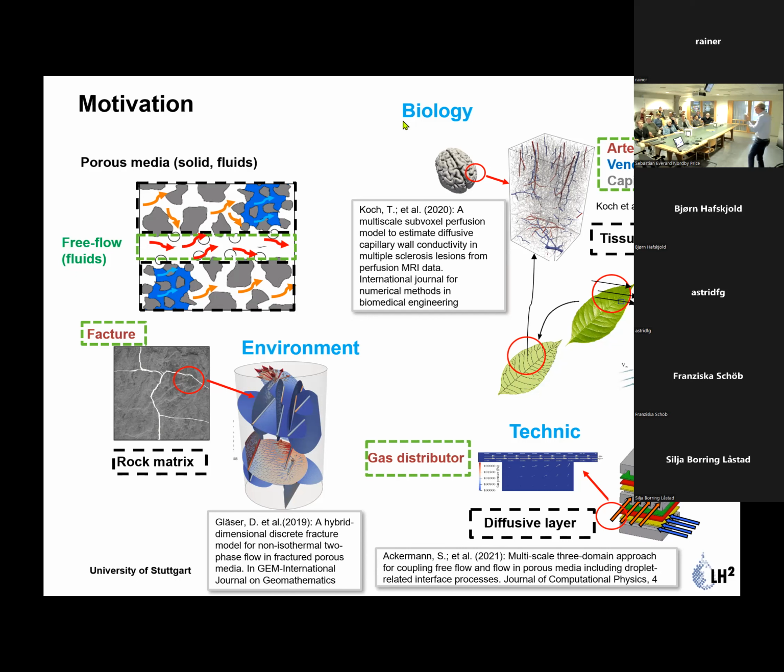There's a big difference to the other ones. In this case, the diffusive layer is a hydrophobic material. So in other words, the water is in non-wetting phase. And that means, for instance, you need now a trick to get out the water. That means to get the bubbles on the top. And of course, you need then a good concept that shares the bubbles into the free flow so that you get enough space again for the oxidant to transfer to the reactive layer with the hydrogen.